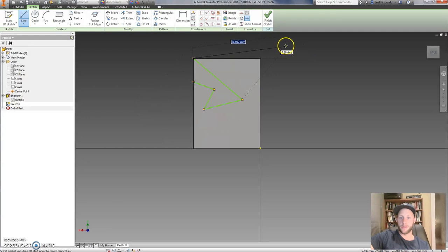Remember to get out, right click and press escape, or escape on your keyboard. So again, we can draw directly onto existing geometry. Remember again that I can move my sketch freely when it is green, because it is unconstrained. So that was just a quick example. I'm going to delete that sketch I've just drawn, and what we're going to do is create some text.